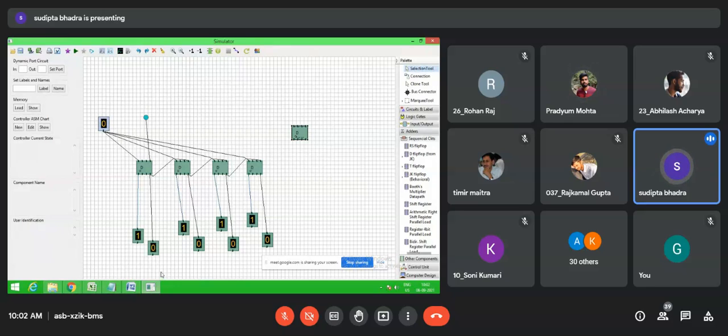So here you can see that the Q is at pin 4. Here all the Q outputs are 0 now. So let me change the bit switch. Here it is serial in parallel out, so first the input will be given only to the first D flip-flop.